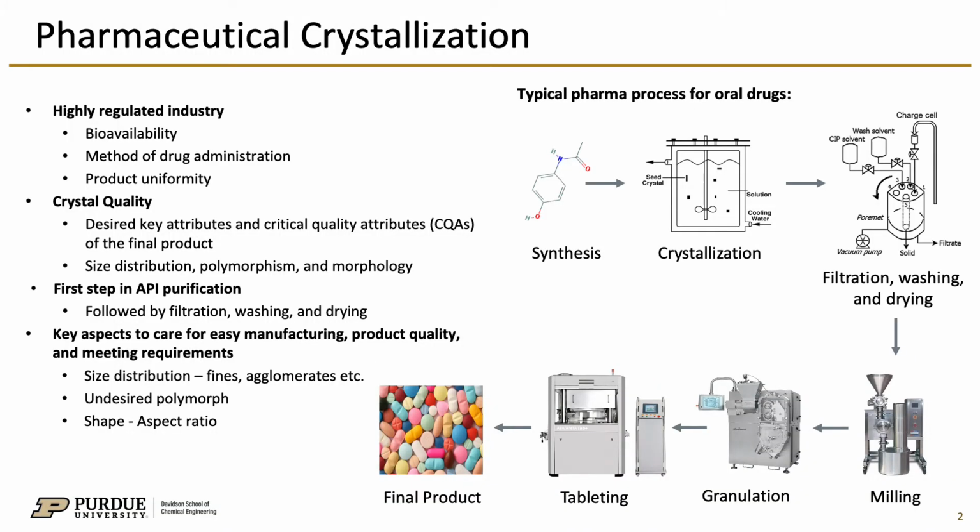Crystallization is the main particle formation and the first purification step in many industrial processes, especially in pharma. Almost all the drug compounds, which are called active pharmaceutical ingredients, are produced by crystallization processes in different modes, such as batch or continuous. This step is crucial for dictating the downstream operations and final drug properties that are strictly regulated by administrations. Based on the required product properties, which we call key attributes, generally the crystallization step is studied first and adjusted accordingly.